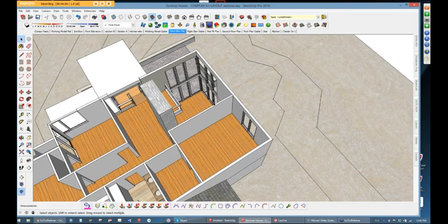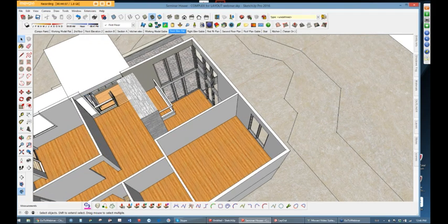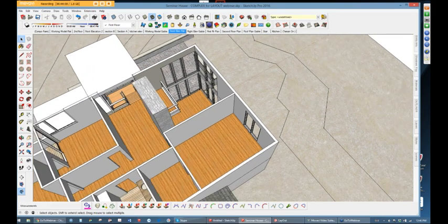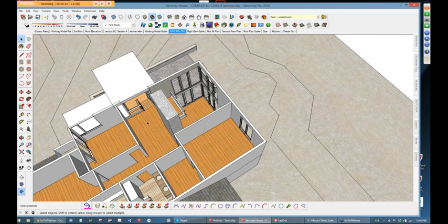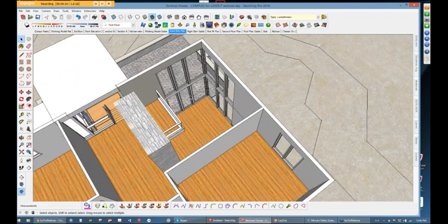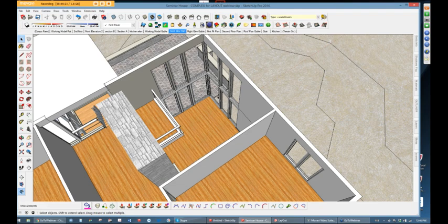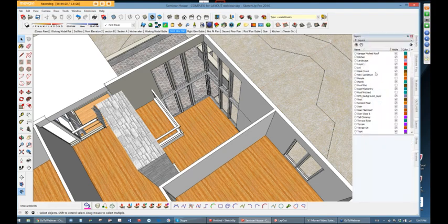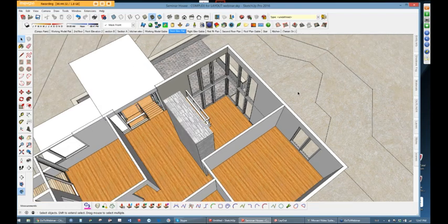Now it doesn't have anything to do with scenes. It can if we want to work this with the layer. But what I want to do is build a plane inside of this, behind this wall, so I can mask or block off everything that's back behind there. So how do you do this? First I want to make sure I'm on that layer, mask. So we need to go to layers, mask front, and pick the radio button, so that's our current layer.